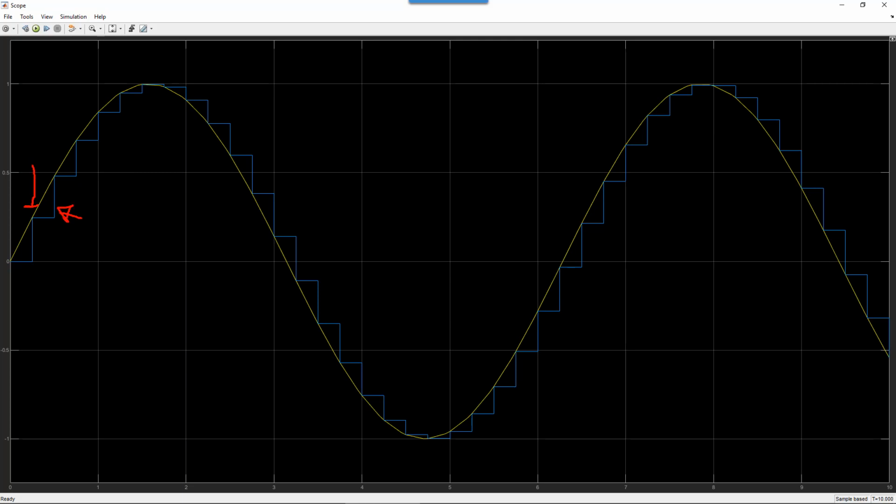And this is particularly relevant because when you have an embedded system, it has to take in its inputs, and then it has to do a calculation before it can update its outputs. So there's always a time delay with a discrete system from the inputs coming in to the outputs being updated. And Simulink lets you capture that delay with discrete systems. Now you can do this using logic.